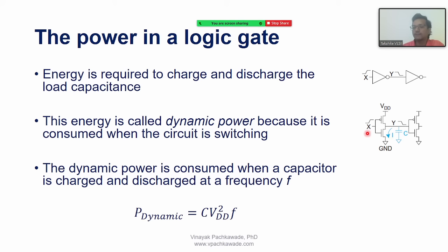frequency. So as I've earlier said to you, X is the input. I am showing here a simple pulse, but what if I have a square wave here that is changing between logic 0 and logic 1? So I have a switching waveform coming as an input, and the circuit is an inverter, so the output will also be an alternating square waveform. It has some frequency, with an on time and off time. So I know the frequency of that input signal, and because of that some dynamic power is being consumed. And how do we calculate that power?